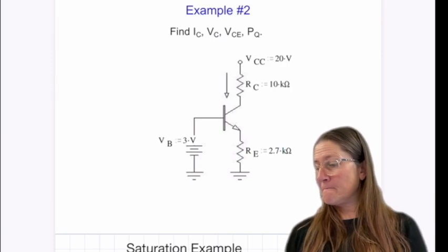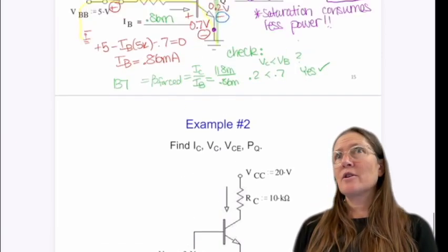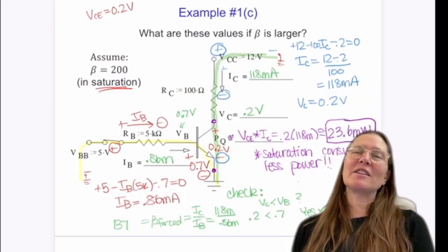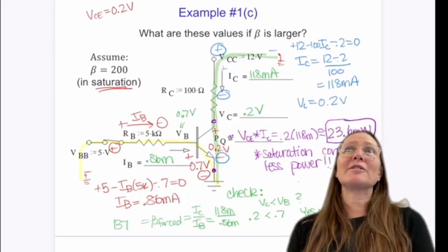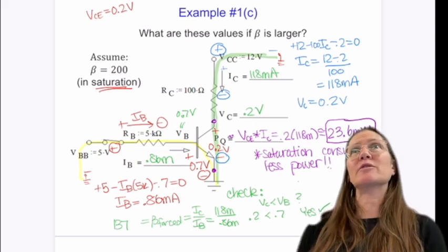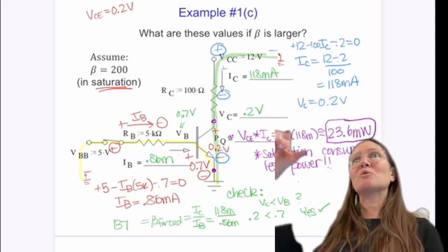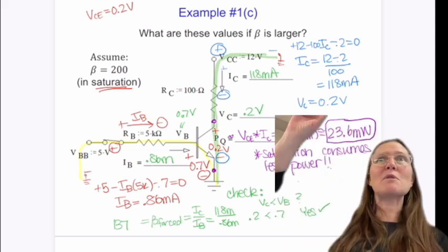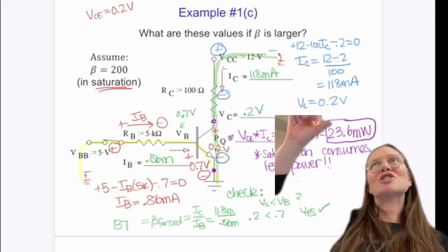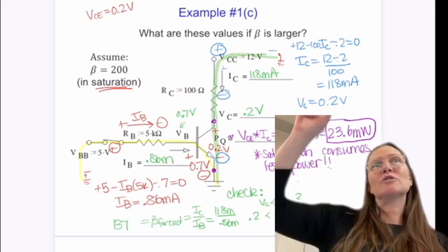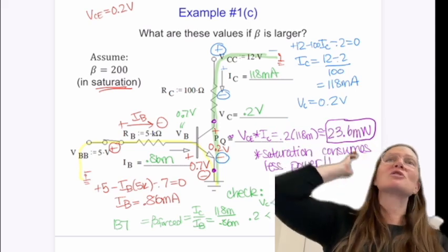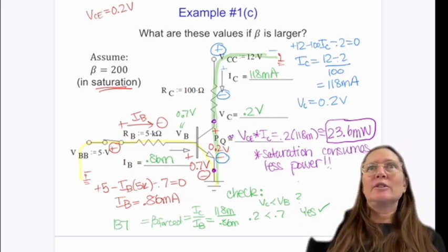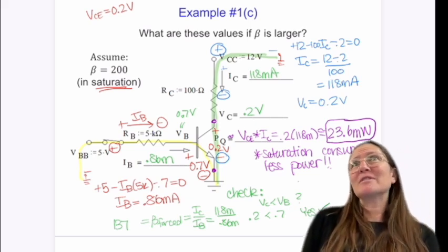Okay. Is RC required, like having a resistor there? That's representative of your motor, and your motor has an inductance and a resistance, as I showed last time. We're ignoring the inductance for now, because when you look at it just in DC, you don't have any change in time, so you treat the inductance as a wire. So we usually just look at the resistance on the DC side. But that is representative of that DC motor.